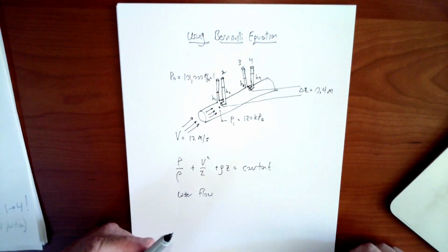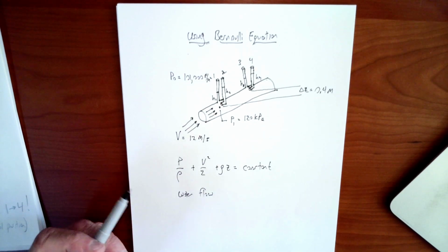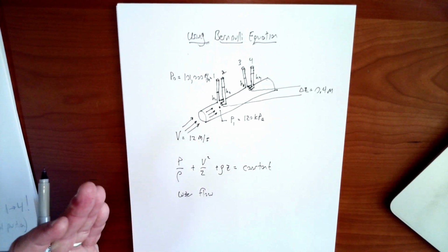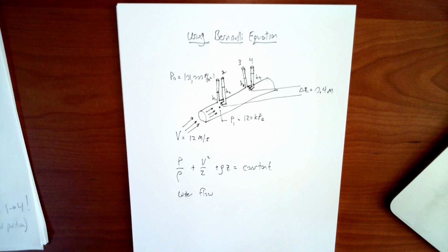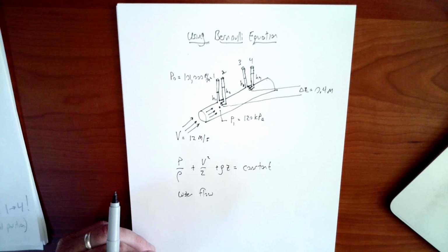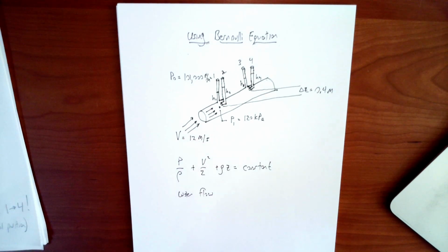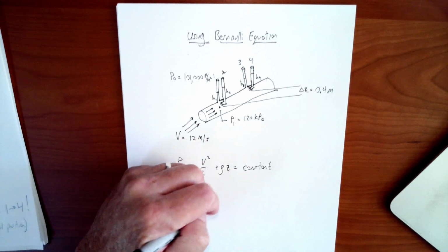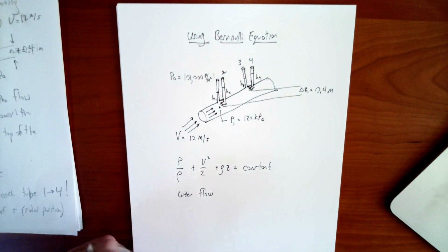Now, first thing that should jump to mind right here is, is that realistic at all? That inside a pipe, the water would be traveling all at 12 meters per second. We know at the walls that the velocity of the fluid is going to be 0. So again, it really depends on the diameter of the pipe and the length of the pipe as to whether that's going to be valid at all. At some point, it is not going to be valid. There are going to be frictional effects creeping into that pipe. But there are times when that pipe flow, if the pipe is short, that we can treat it as a uniform flow, in which case viscous effects are not significant. The viscosity effects have not reached into the center of the pipe. So we'll see how that goes.